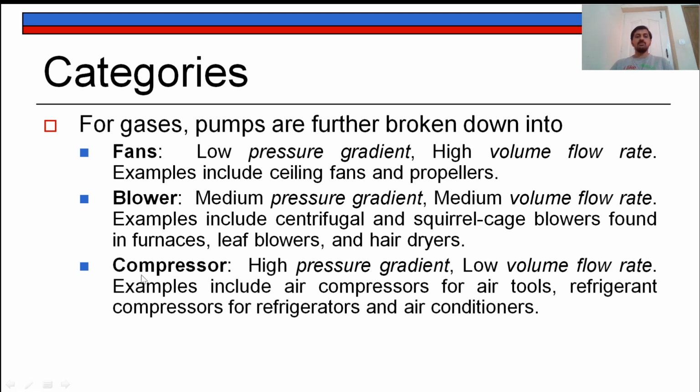In the case of pumps for gases, compressible fluids, the pumps are known by three names: fans, blowers, or compressors. Are you wondering? A fan is a kind of pump for gas, compressible fluid. A blower is also the same category. A compressor is at a higher level, which can deliver highly pressurized gas compared to a blower and fan. So all these three, fan, blower and compressor, can pressurize a compressible fluid, but the range of compression is the only difference among these three.